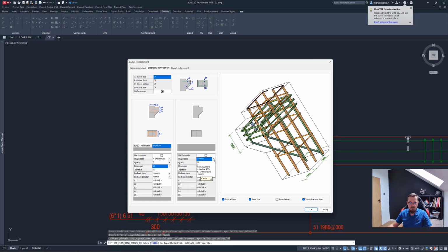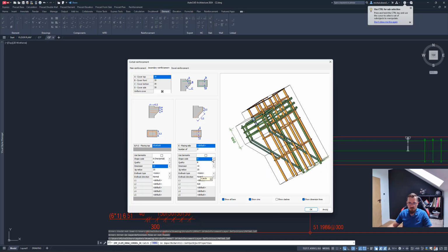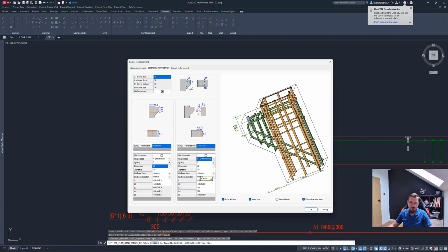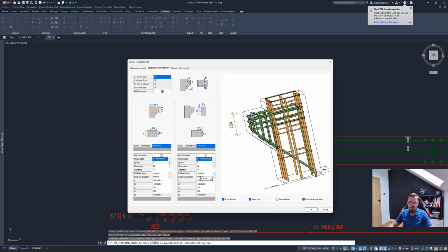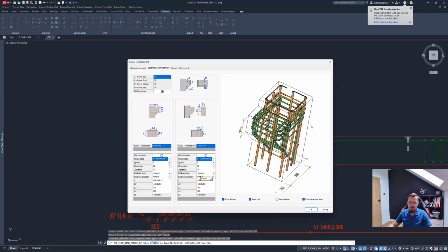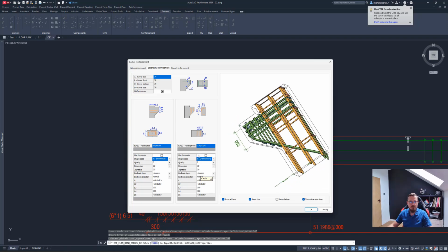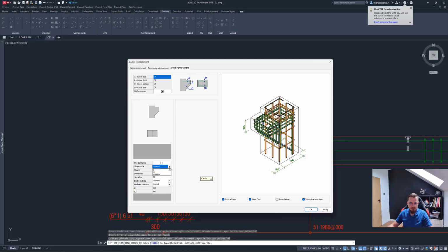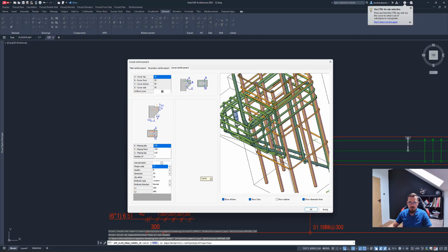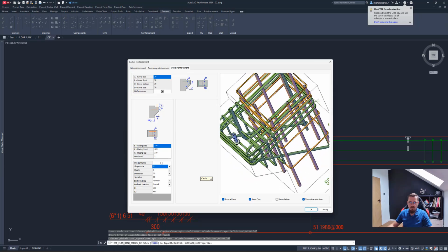And for the other reinforcement, there are multiple ways you can add that corbel reinforcement. As you can see right now, there's really a bunch of reinforcement. If we want stirrups going this way, you can do that as well. So multiple different ways of adding the reinforcement. Let's go with those 51 shapes. And if need be, we can also add some dowel reinforcement just to demonstrate that. So that's a bar like this.